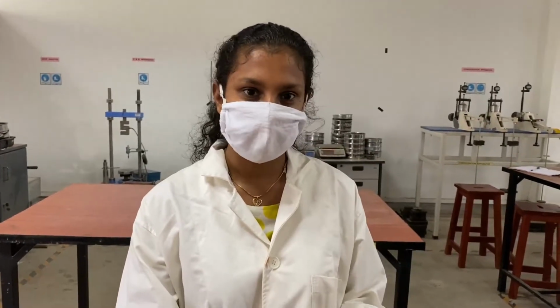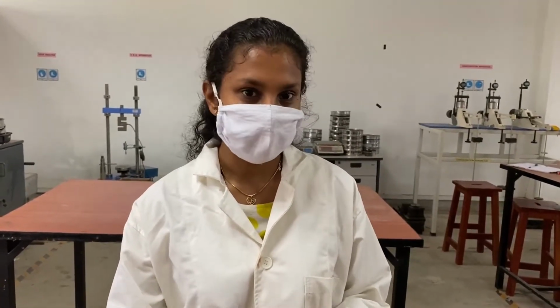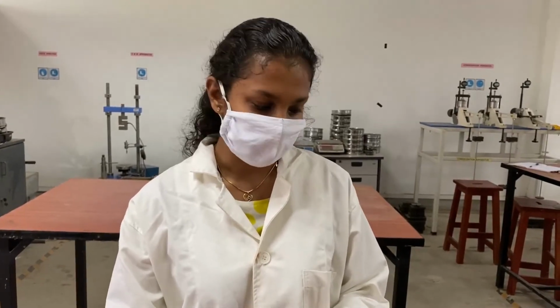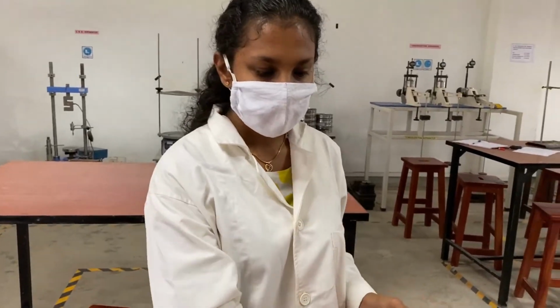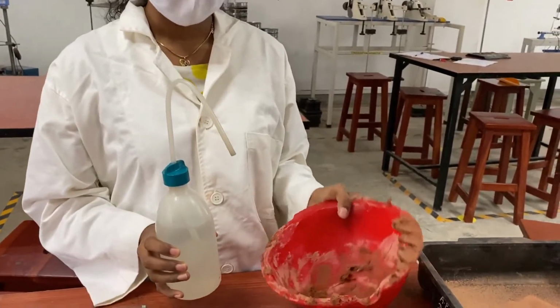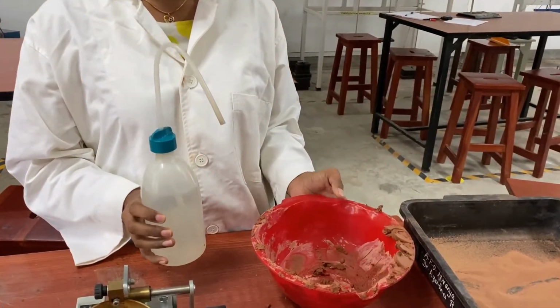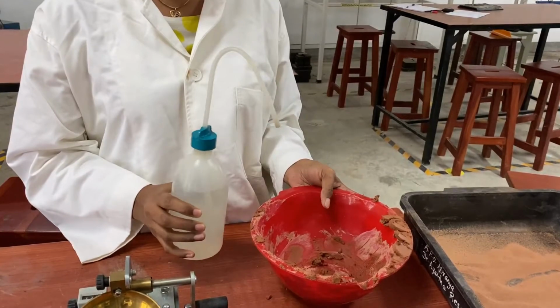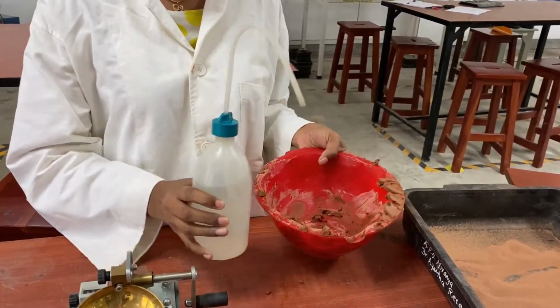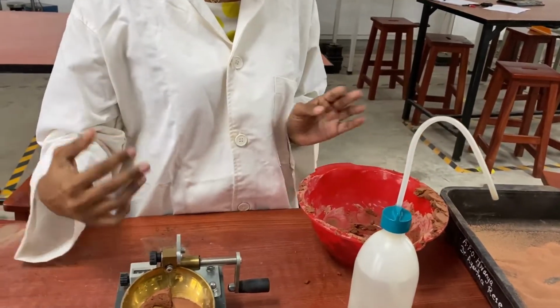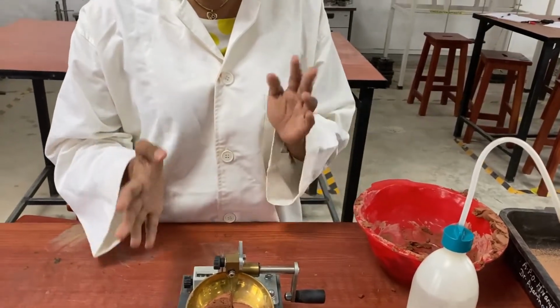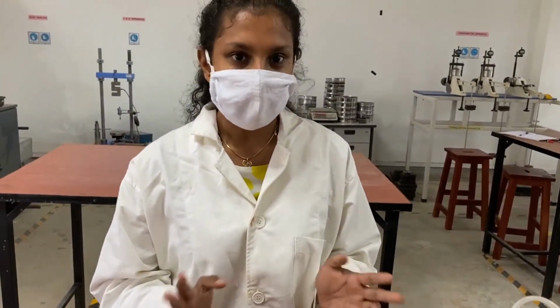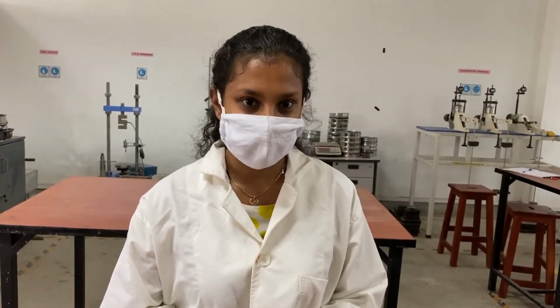Okay, so we have done one of the trials. Similarly, you will have to do another 5 more trials to complete this experiment. For that, you can use some distilled water, and for the amount of soil sample, you can vary the amount of distilled water you add and make a uniform paste and do the same procedure as it goes. The blow count should be from 10 to 50. So you can take around 5 readings and continue with the rest of the calculation.